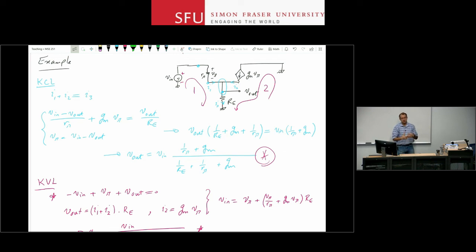And in most cases, you just want to focus on one of these stages at a time, right? So you want to focus on the power amplifier stage at the very end of this chain, and the rest of the circuit is not of importance to you. It is providing the input signals to the last stage, but you're not concerned with how they are operating. So what you want to do is simplify the rest of the circuit, whatever is behind your stage or after your stage, and just keep your focus on whatever you're interested in.